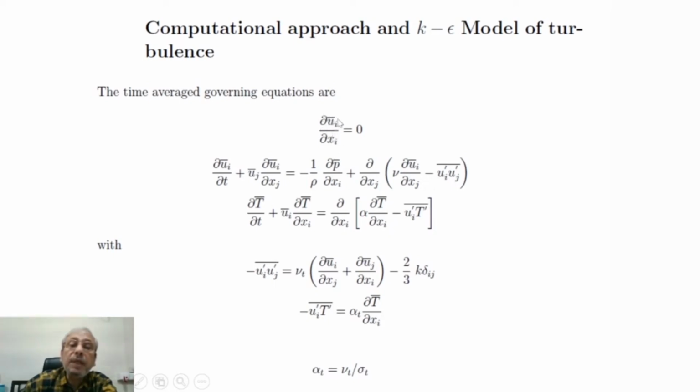This can be depicted as del x of u bar plus del y of v bar plus del z of w bar equal to 0. So this is a continuity equation. As I said, divergence of ui bar. Ui in Cartesian coordinate, ui bar means u bar, v bar and w bar.